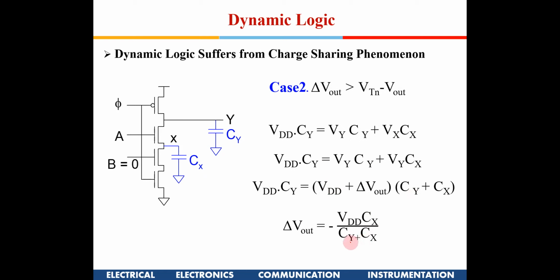Here I had made some mistake on the slide in the last class. So here, now we are assuming that Cx is very large, right? As the charge is getting shared from here to here, it cannot reach the maximum value, because that much charge is not available from Cy, since Cx is now large. So what happens is it will keep getting charged till these two voltages become equal. After that, it cannot go beyond that, so it has not reached the maximum value.